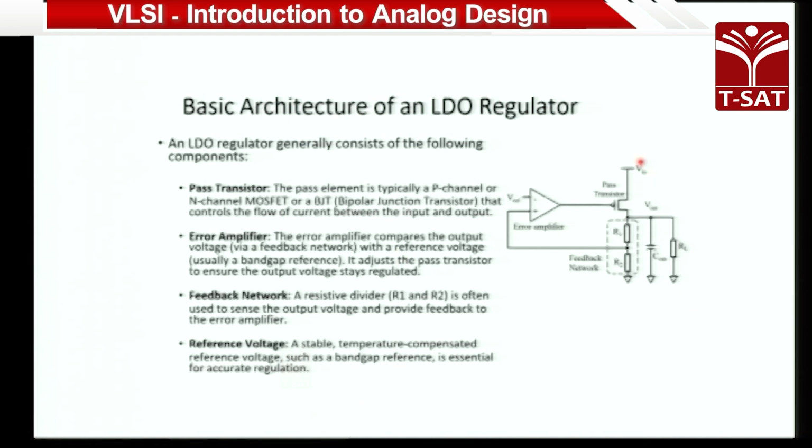I was about to come to that anyway. If I show you this particular diagram, this is the input voltage of the regulator, and this is the output voltage of the regulator. This is the power supply. If there is noise here, this noise gets to the output through a capacitor between this and this, which is not drawn here, but it is there as a parasitic. So you have to envision this capacitor and take steps to reduce the noise from here to here.